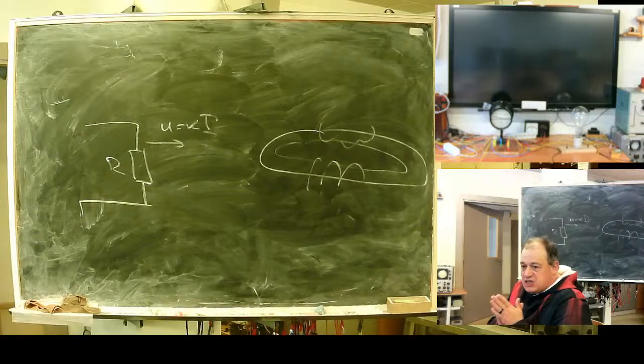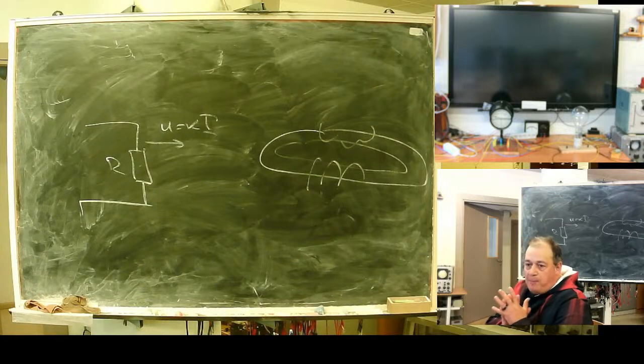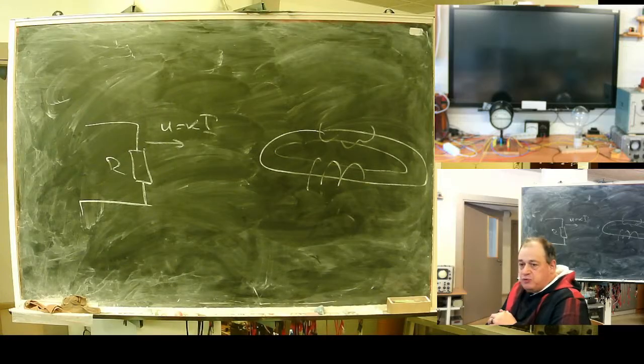And a very serious point of concern: field current, excitation current of large machines. When we deal with a large generator, its protection, excitation system or power system stabilizers, the problem is voltages up to 2 kilovolts, currents up to 3000 amps.